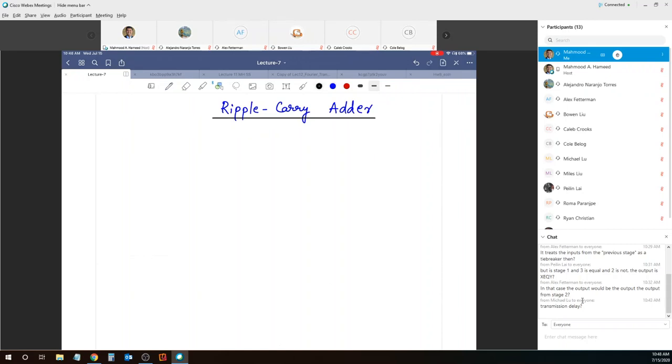And I'm trying to write expressions for sum and carry out. So S sub i, the sum at any ith position, can be written as x sub i exclusive or y sub i exclusive or C sub i.